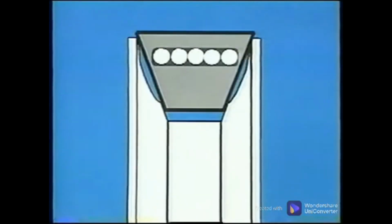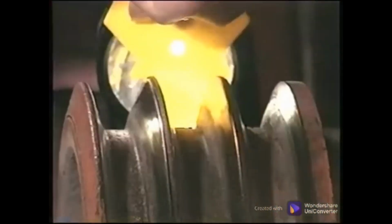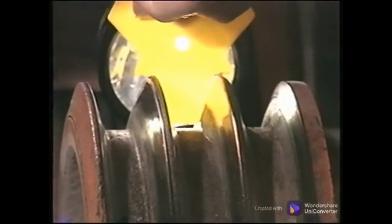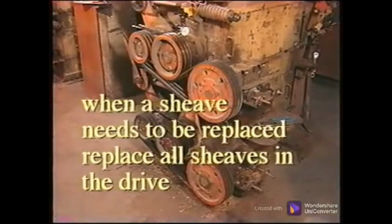However, this check alone does not ensure the sheave is not worn. If the sides are dished, the bottom corners of the belt may hold the belt out, but will wear quickly and work down in the groove. The best method is to use a sheave groove gauge, checking each groove, and then replace a worn sheave. When a sheave needs to be replaced, replace all sheaves in the drive, which increases the life of the belts.